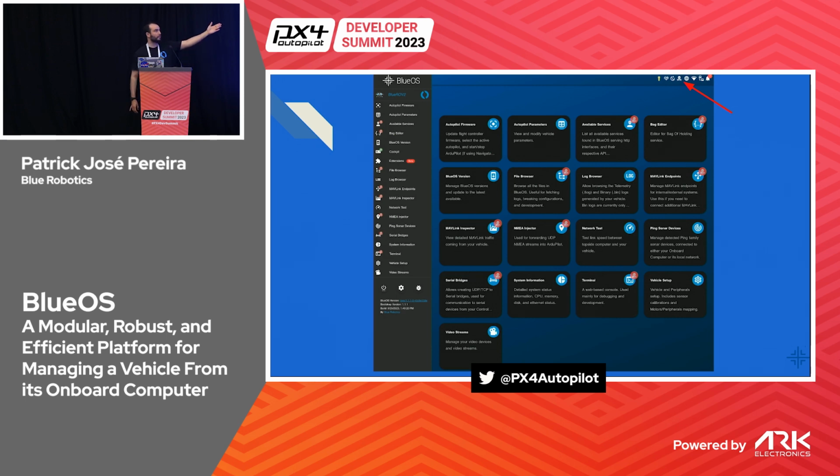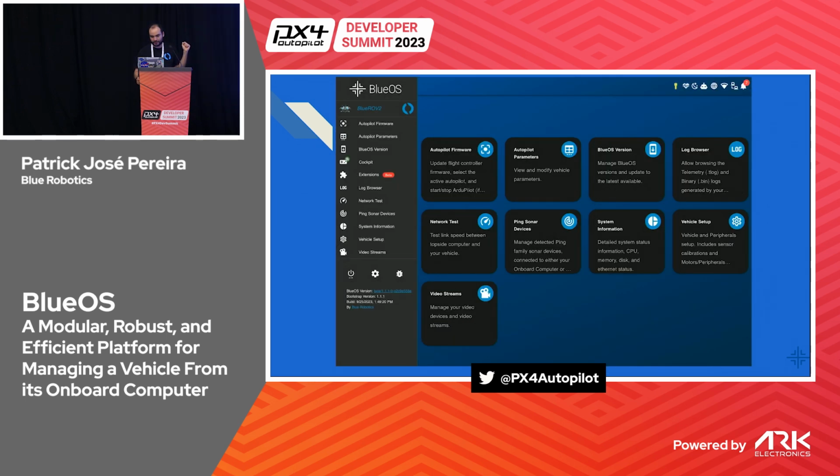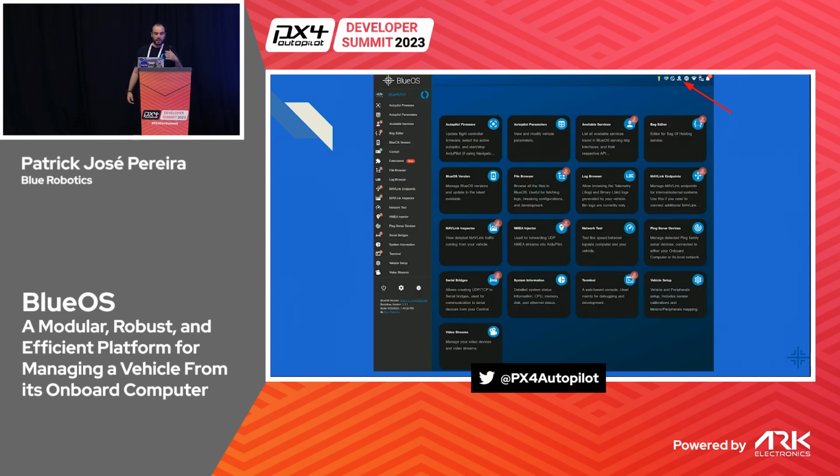And if you enable pirate mode, that you can see in the other image, we have this happy robot icon. If you click on it to enable pirate mode, you're going to have full power over the interface. You're going to have everything that is really complex about the robot and can be dangerous for a normal user to mess up. In this mode, we can take a look at the available services, modifying the settings of the front end directly. You can have file browser, MAVLink endpoints configuration, MAVLink inspector, NMEA injection, and also bridge for serial configuration, and also direct terminal access.